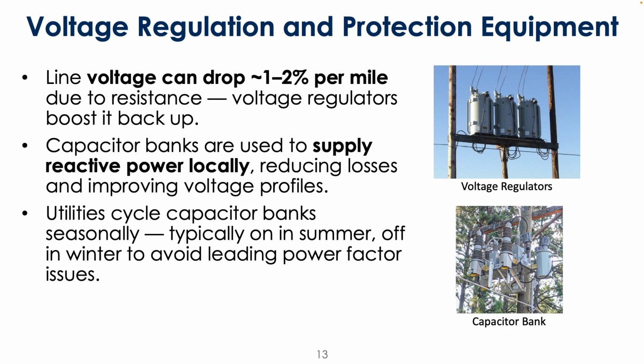If a power factor is 1, then kVA and kilowatts are the same. But a transformer doesn't care about the power that you're using to generate useful work at the end. It just cares about the current going through it, which is why we have this power factor that you have to think about.